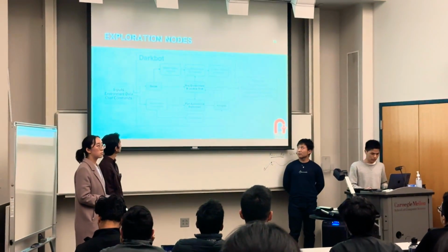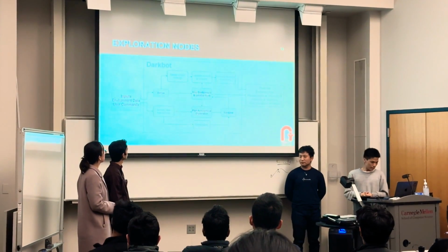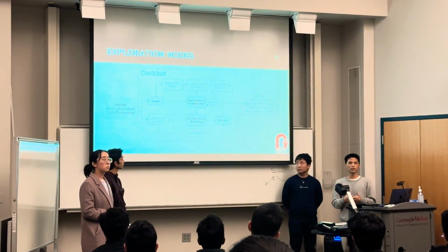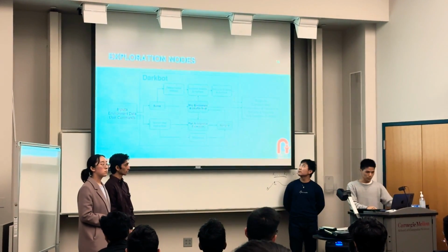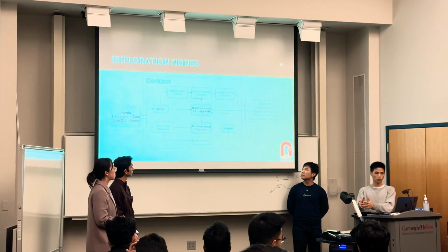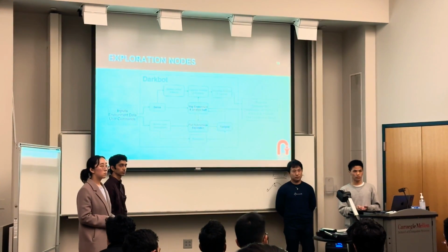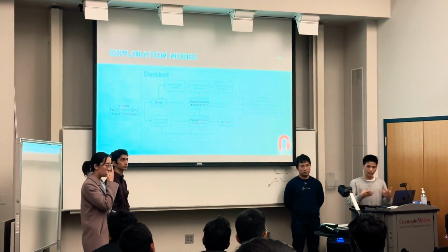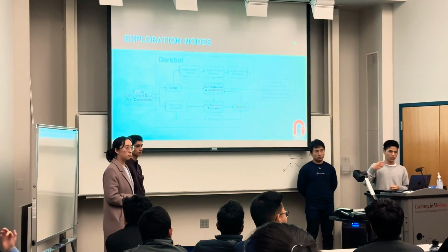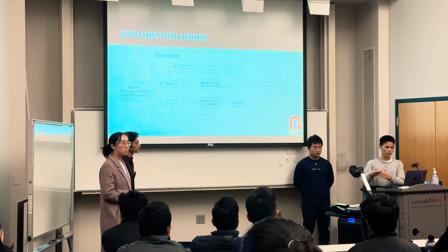So here's how it works. The robot senses from its device, and then it maps the environment around it. At the same time, it tries to localize itself. The robot then plans for the next feasible action and moves to that position accordingly. With the new position and the new system state, the robot remaps the environment and relocalizes itself. And this loop keeps going until all people have been saved or the time limit has been exceeded.